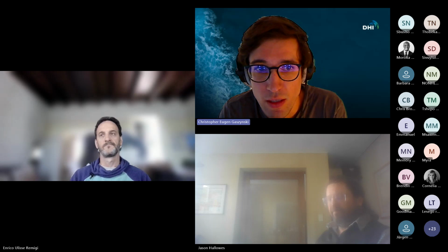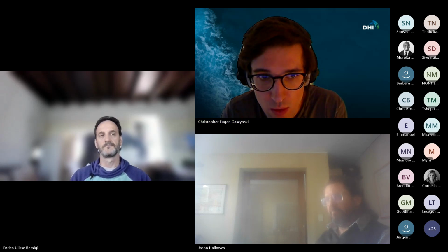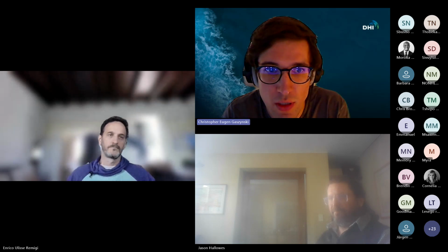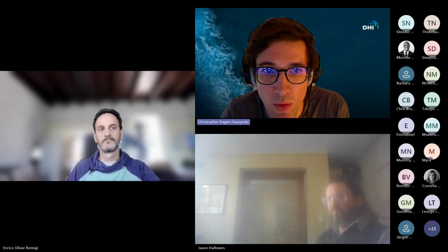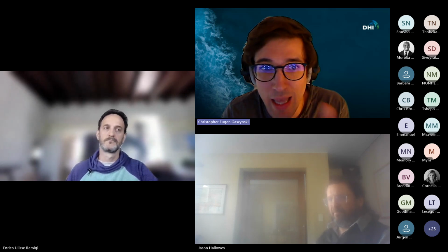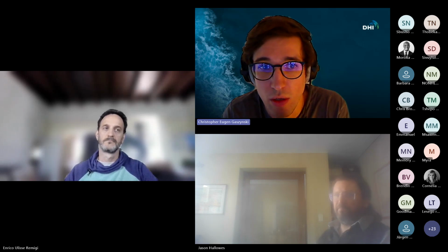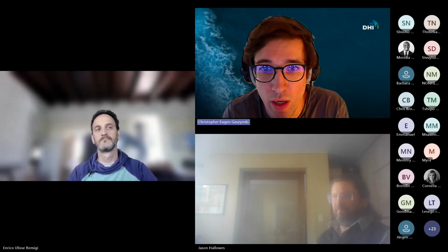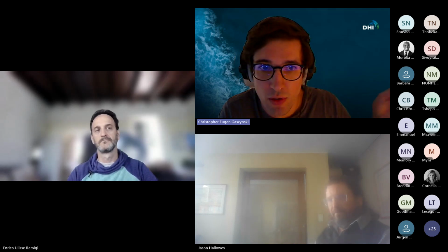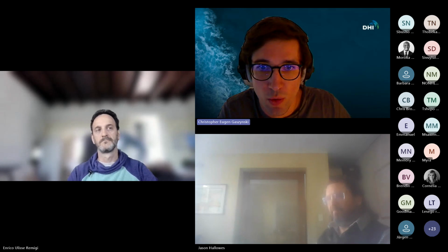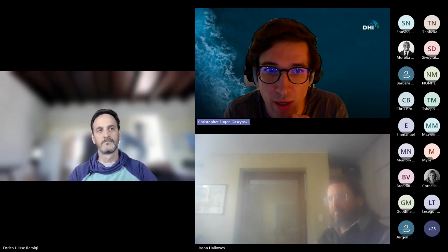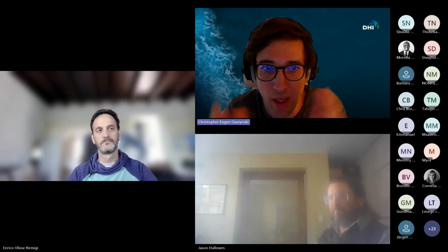So as Chris Brook had mentioned, with hybrid modeling, we're doing that more and more in our projects for N2O emissions, for instance. That's a big application that we see with this nitrous oxide, is that the model's just slightly lacking with the accuracy that we need. So we're trying to now research and develop methods where we train data-driven models to correct the mechanistic models in terms of the predictions that they make for N2O emissions. So it's kind of like a leapfrogging back and forth between the two domains. And that I think has a lot of value instead of just relying solely on one application or the other.